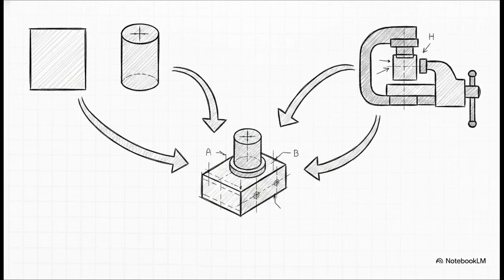To make this work, there are 3 mandatory ingredients you're always going to find when dealing with position tolerances. First, you need basic dimensions. These are the theoretically exact untoleranced numbers, usually enclosed in a box on the drawing, that locate that exact true position. Second, you need to define a tolerance zone shape, which is almost always cylindrical, denoted by the diameter symbol. And third, you need datum references to lock down your part and constrain its degrees of freedom.